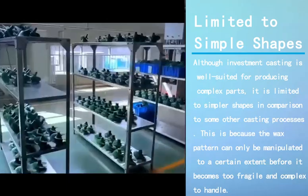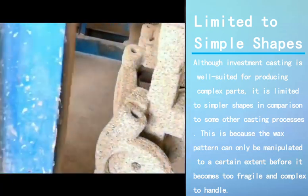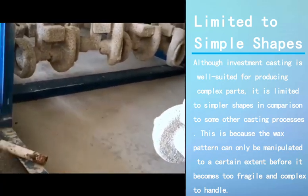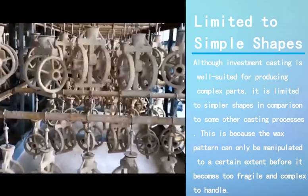Limited to simple shapes. Although investment casting is well suited for producing complex parts, it is limited to simpler shapes in comparison to some other casting processes. This is because the wax pattern can only be manipulated to a certain extent before it becomes too fragile and complex to handle.